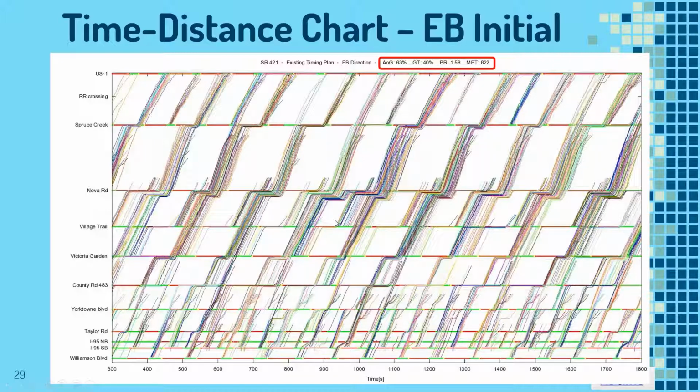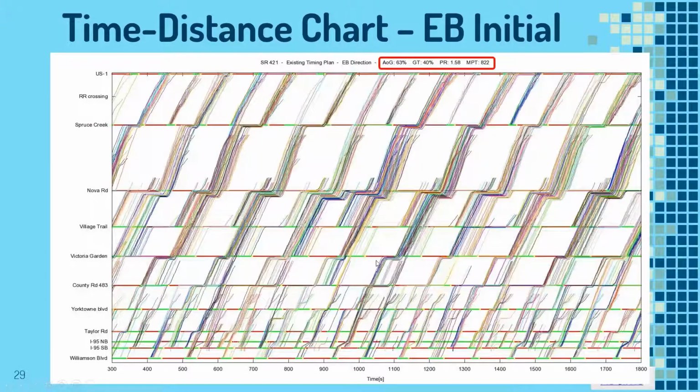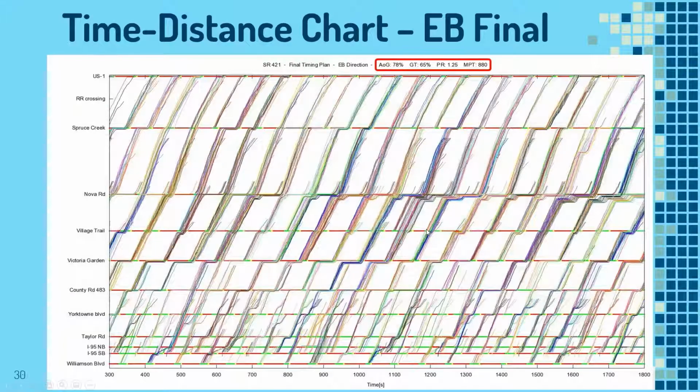So you can see, for example, how in the eastbound direction, the initial signal timing plans had a lot of delays at certain intersections, and then for the same traffic flows, once that plan was optimized, you can see that the flows through the intersections are much better. It's still not perfect, because for a number of reasons like geometry and varying speed limits, this corridor has, I believe, three different speed limits on this set of 11 or 12 intersections.